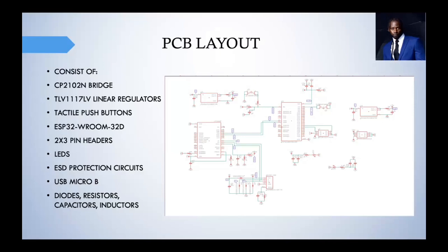For the PCB layout, originally the PCB layout consisted of the bridge, and it had a linear regulator, and they also had a switching regulator. Unfortunately, one of the regulators just wasn't able to really get it to work, and we ended up switching out that switching regulator and just using 2 linear regulators.